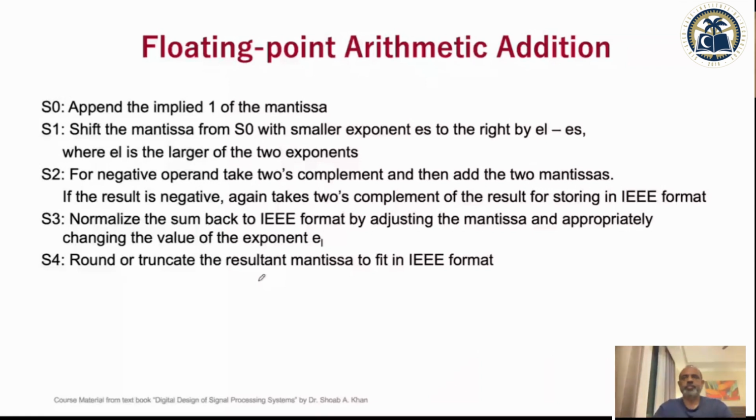Once you have exponentials and you are multiplying, exponentials are to be added, fractional parts are to be multiplied, signs are to be multiplied. Then you see what you have. The same is the case with addition. First, both exponentials should be aligned, only then can you add numbers. So you need to do the alignment, then add, then move the result again. It's a lot of things that you have to do in order to convert numbers and do the arithmetic in the floating point format. But fixed point is, I'll be just finishing this lecture.